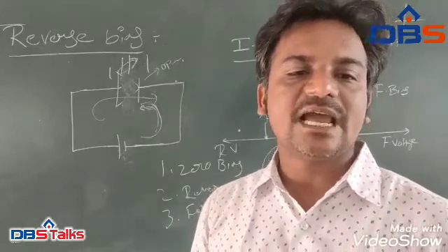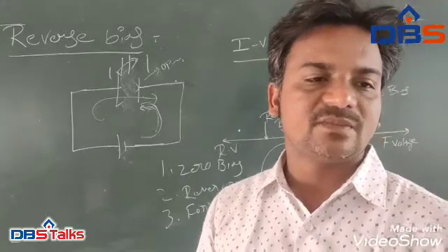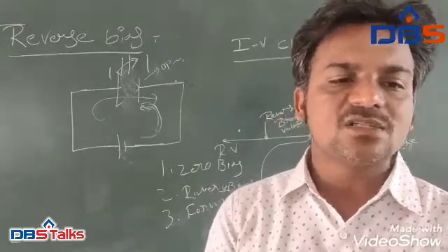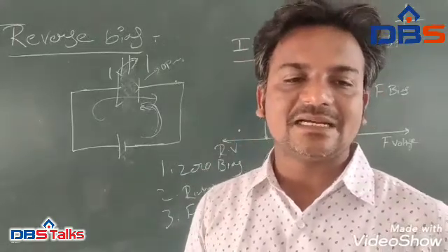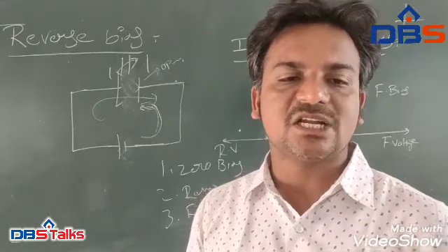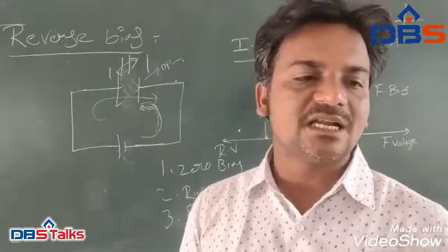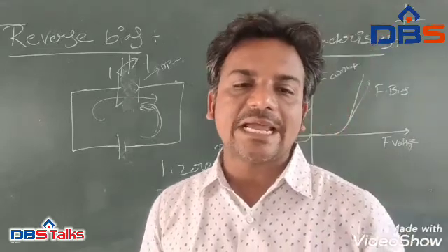This is called forward current and is referred to as IF. Likewise, the holes generated in the N-type material, the minority carriers, find this situation and move across the junction in the opposite direction. This is known as reverse current and is referred to as IR.